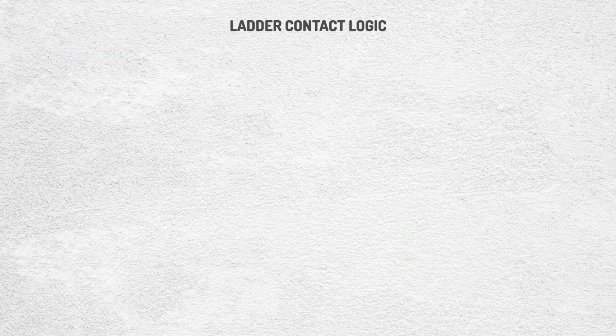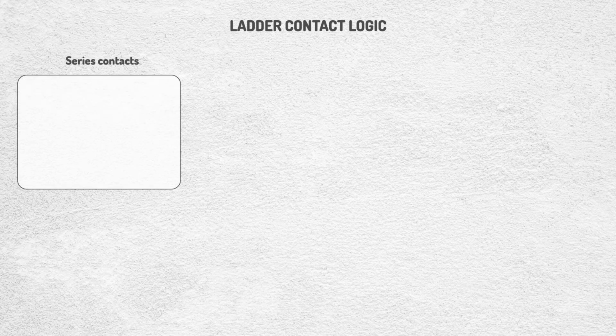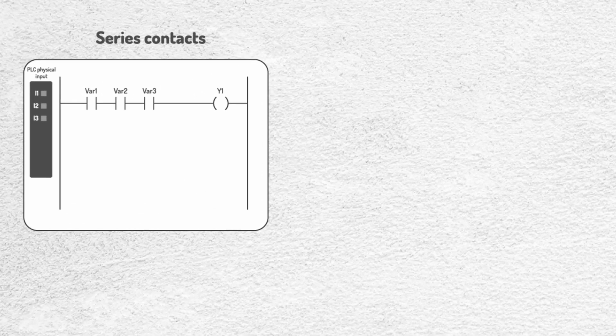Let's review some contact logic in ladder, which works very similarly to the behavior of real electrical contacts. When we place contacts in series in a program and they are associated with digital inputs, their operation depends directly on the state of the PLC's physical inputs.